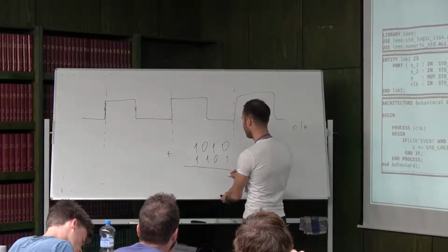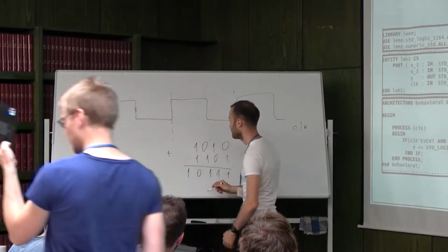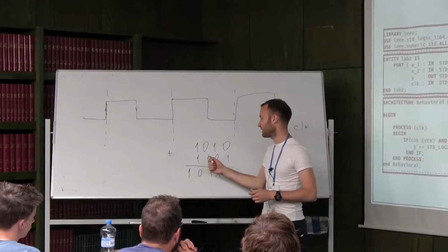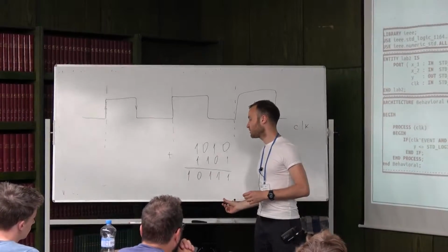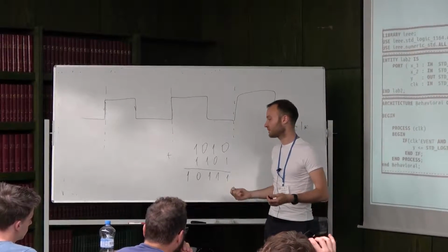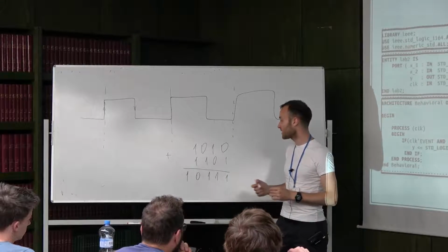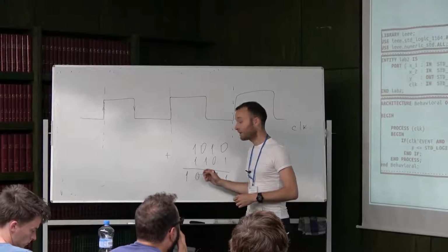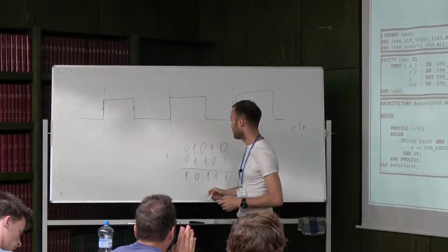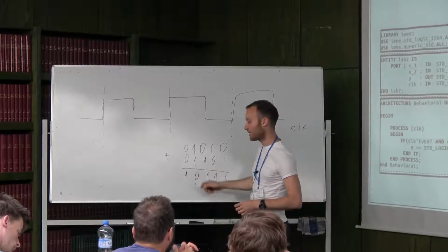So we add it bitwise, and in the end, our result is larger than the number of bits in the inputs. If we don't handle this explicitly, we will end up with an overflow error, so we lose our result. It's not only about losing precision, we get a completely wrong number. That is why we allocate an additional bit and augment our inputs with zeros, which do not affect the result but make the input and output size fixed.